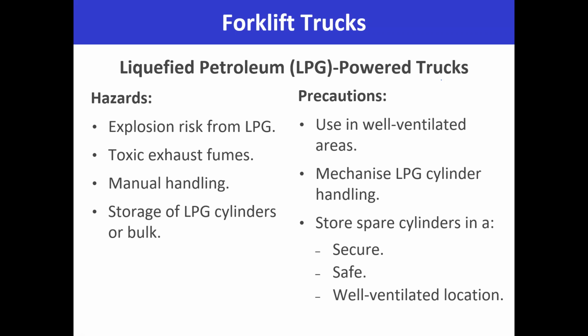LPG powered trucks, their hazards are explosion from the LPG, toxic exhaust fumes, manual handling and storage of LPG cylinders. Precautions are to use them in a well ventilated area. So don't use LPG trucks in an area where there is poor ventilation. You need to provide good ventilation if you want to use LPG trucks.